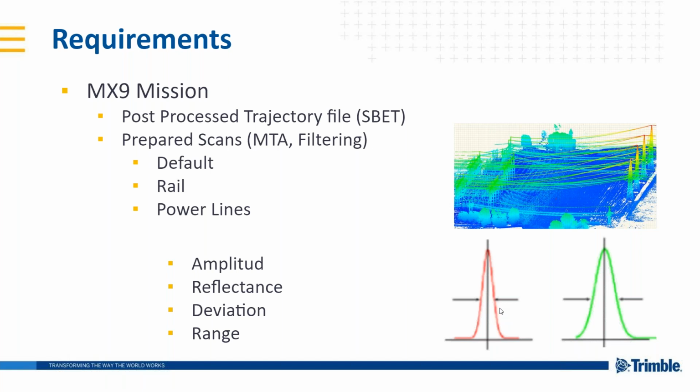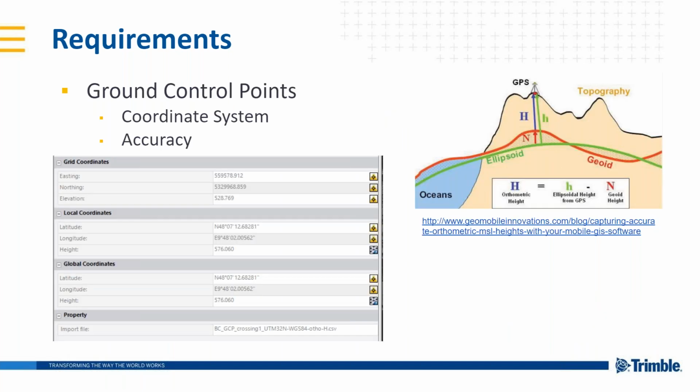That is the case of the railway application, where the rail is always at a constant distance to our laser scanner, but the shape of the rail is very sharp and the incident angle of our laser beam changes in a very small distance when we measure. So basically, if you are interested to perform any further filtering, you will play around with those four parameters.